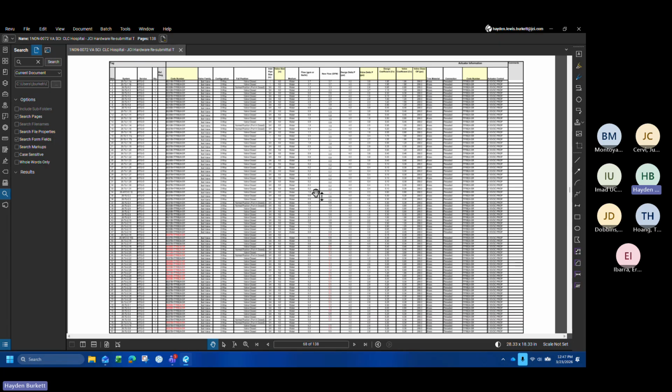That's interesting. I don't necessarily want to speak for mechanical on this, but my understanding is, if you're seeing some sort of manual isolation valve, it's for isolating your controls actuator. If you're seeing a circuit setter, like a dial valve type thing, or a CT valve of some sort, you typically don't want to touch that one.